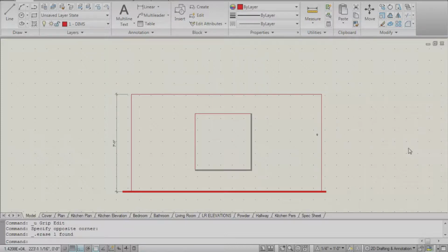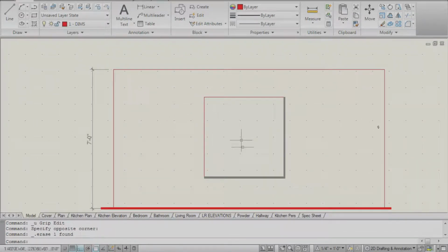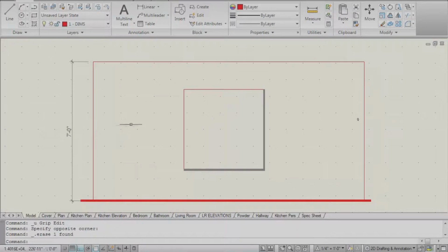Anyways, look at this interior elevation. It's pretty basic. You have your wall, you have your image, you have your finished floor line, which is always supposed to be thicker, and this is a pretty short wall of 7 feet. Anyways, I want to add a wall paneling at the back. I want to add a wooden paneling, have some sort of nice look to it.